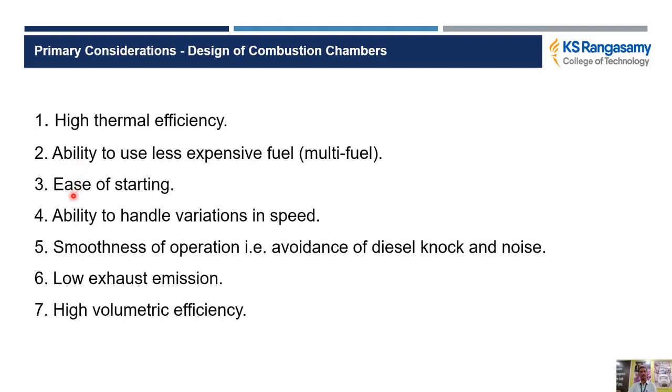The next thing is ease of starting. When designing the combustion chamber, the engine should start even in very cold conditions, easily and without any external aid. That is also a parameter to consider. Another thing, it should be able to produce variable speed under variable requirements, so the engine is dynamically able to give variable speed. Second, smoother operation. When running a diesel engine, we can hear noise, sound and vibrations. That has to be avoided with a proper combustion chamber design.